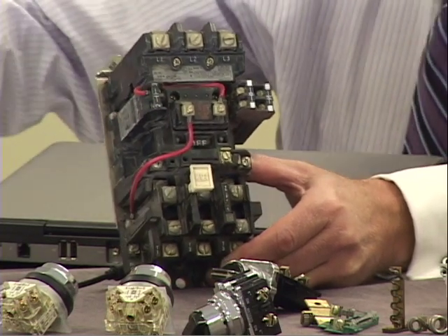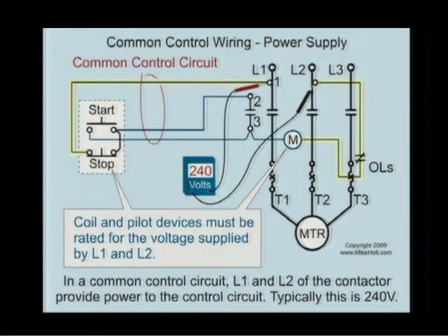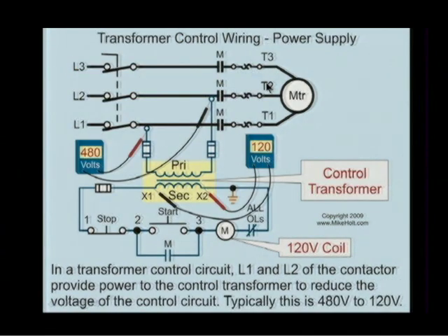All right, so the point I'm trying to make here is how do you get power for this control circuit? We're coming off of the branch circuit supplying that actual motor. And there's a lot of rules associated with that, but right now that's how we get a source.